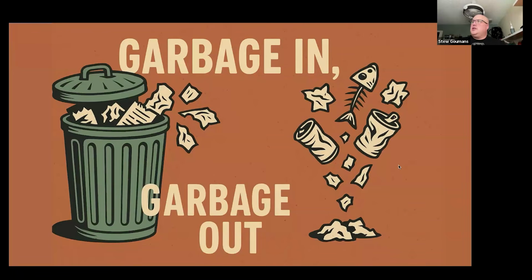Yeah, I got one here that follows back a couple slides. What is the recommended amount of collection points when using stop and go surveying in a large area versus an office? Great question. We have some slides later on that show the distance you should have between your survey paths. But to answer at a very high level now, when you collect a data point, we extrapolate in a 3 meter radius from that data point. So as long as there's no more than a 6 meter gap between your data points collected on the survey path, you'll never see a gap in your coverage.